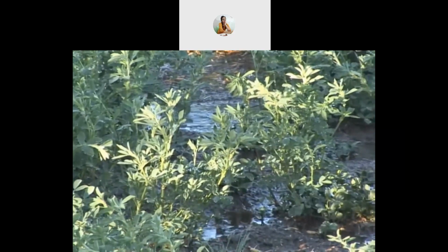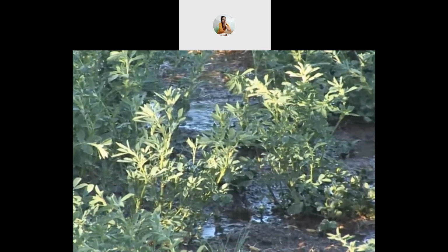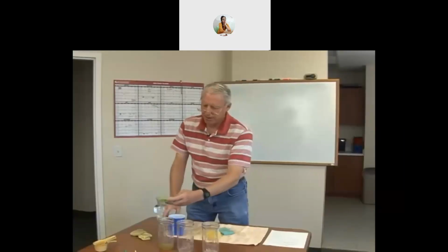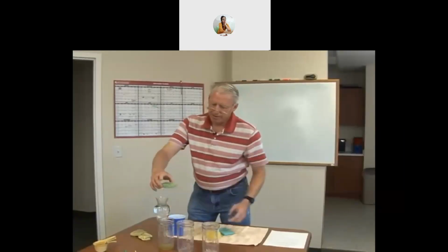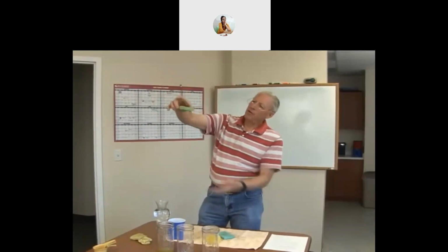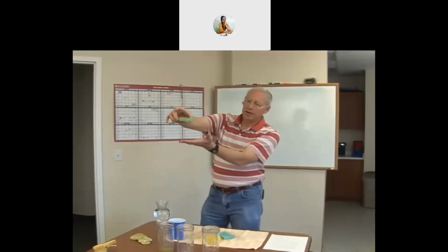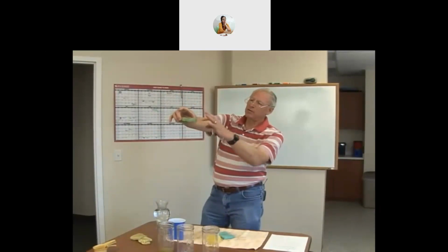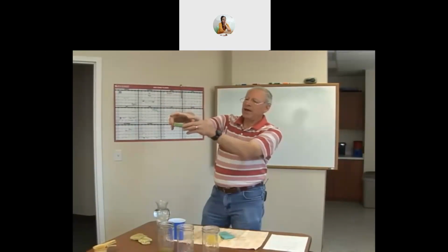This is what you would do when you're irrigating, only you would want to calculate how much water you need to apply, and you need to understand how much water your irrigation system puts on, etc. Okay? Now, you see that there is no water coming through the sponge. There's no water coming through the soil profile. This sponge is now at field capacity.